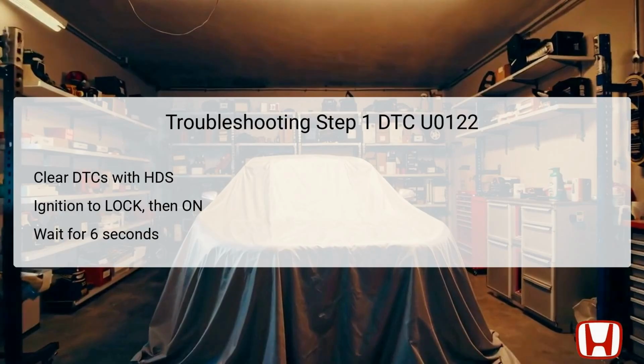The initial step in resolving DTC U0122 requires technicians to clear any existing diagnostic trouble codes using the HDS. The Honda Diagnostic System is a crucial tool for this process, allowing for accurate readings and resets. After clearing the DTCs, it's important to turn the ignition switch to the lock position and then switch it back to on. This action ensures that all systems reboot properly and can help in refreshing communication across modules.